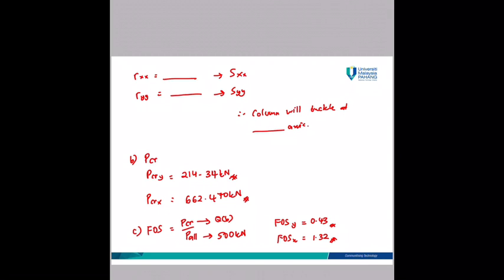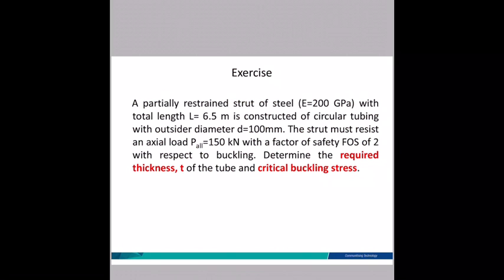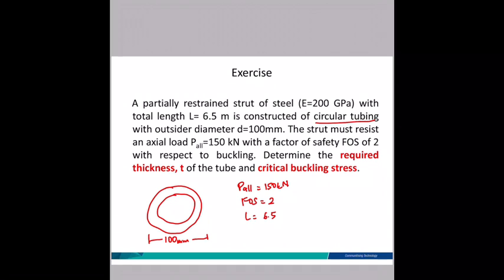Okay, for here you calculate. Please do the rest of the calculation. And please do this exercise. And it is partially restrained. Partially restrained means it is a pin-fixed connection. So here, what is your inner diameter? After you get your inner diameter, then you can calculate the thickness.